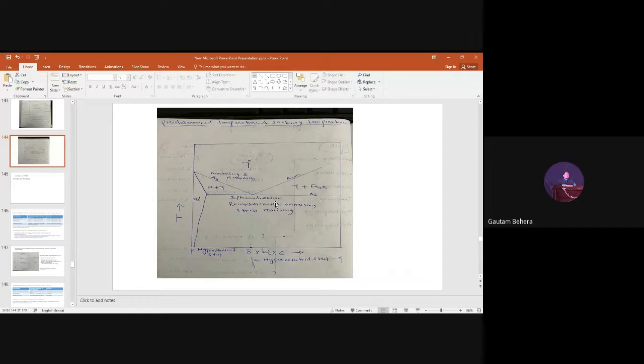But if there is heterogeneous nucleation only, and the distribution of cementite is not uniform, then discontinuous cementite is good. But it should not be needle shaped or completely irregular in shape. That is also detrimental, because crack initiation points are there, or it may behave as a crack or stress riser, right?